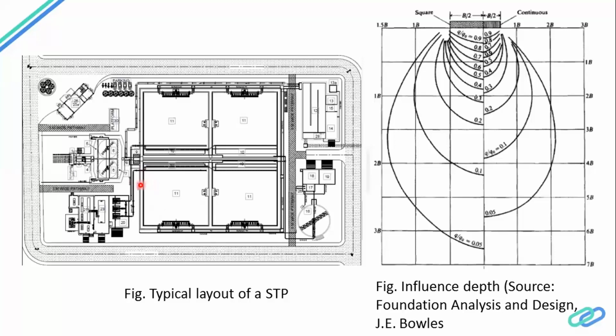So here I have a wall footing. Say I am assuming it may be 4 meters wide. So influence will be 4 times the width of the foundation, so it's 16 meters. And maybe the depth of the foundation may be 2 meters. So 16 plus 2, it's 18 meters. So I'll round off and give a 20 meters deep borehole. So this way we will give the depth of the borehole.